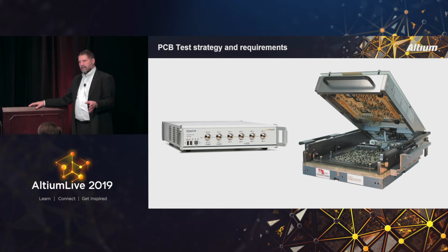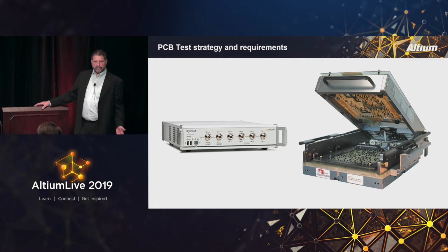Typically I like to go with a 25 mil pad with a 50 mil pad to pad pitch. That would be a pretty standard test configuration, because you can get them in, but they don't necessarily drive your design so hard that it's really difficult to get those in.